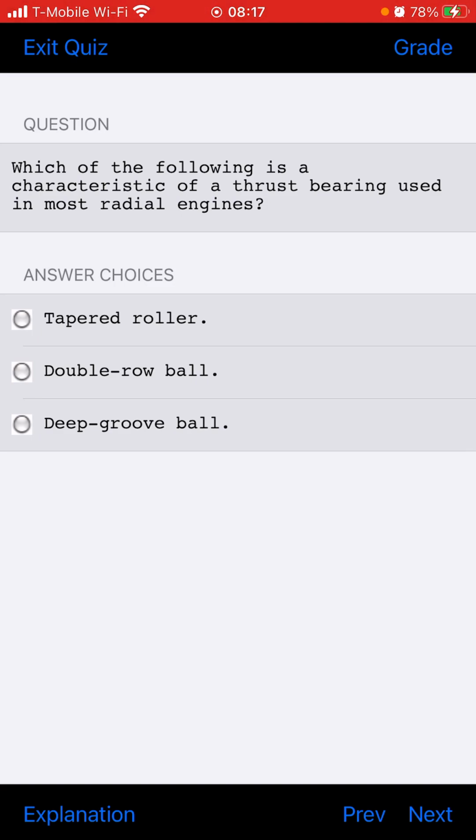As it leaves top dead center, it accelerates from zero velocity to a maximum velocity, which is reached when it is 90 degrees beyond top dead center. It then decelerates to zero velocity at bottom dead center. So maximum velocity is at 90 degrees after top dead center. We have to come back to that one because it's kind of confusing.